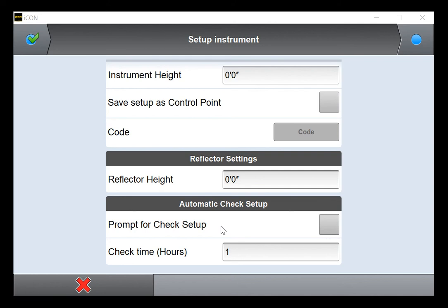Best practice when laying out for a long period of time is to check your total station's levelness and remeasure one of your reference targets at regular intervals, whether you've received any error messages or not. I typically check mine about every 30 minutes, whether I've received any prompts or not. There are many factors that cause the total station to lose setup integrity through the course of the day, and it should be consistently checked and reset to maintain high layout quality.